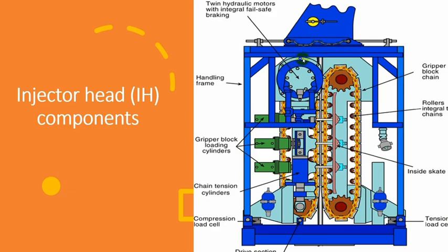So this sprocket will drive in this direction, clockwise, and this one anti-clockwise. This is in case of running in hole with coil tube. In blowout of hole, it is the reverse: this sprocket will rotate anti-clockwise, and this will rotate clockwise.